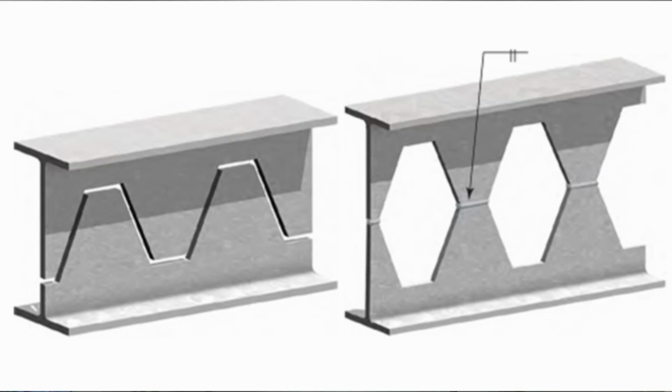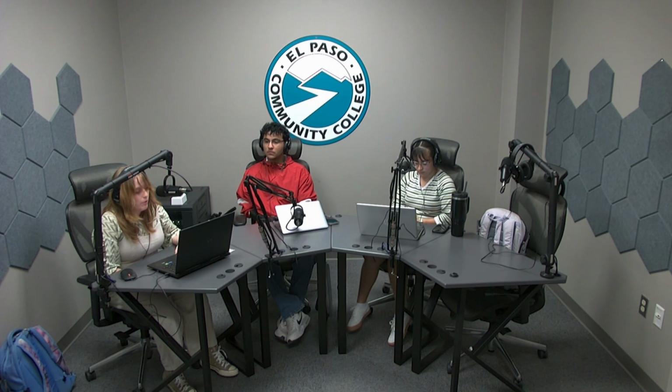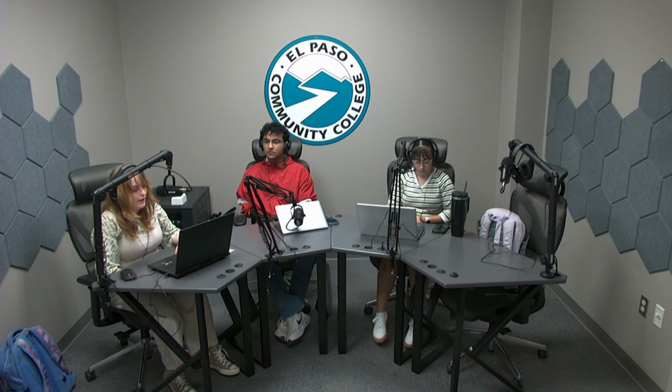The castellated beam, which there's a picture of right here, is produced by flame cutting the web of a wide flange section along a zigzag or arcade path, then reassembling the beam by welding its two halves point to point, thus increasing its depth without increasing its width. This greatly augments the spanning potential of the beam, provided that the superimposed loads are not exceptionally heavy.